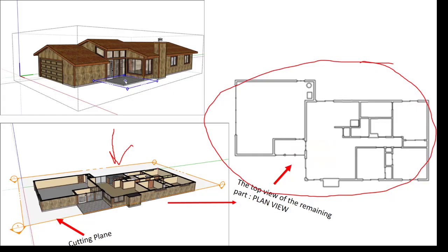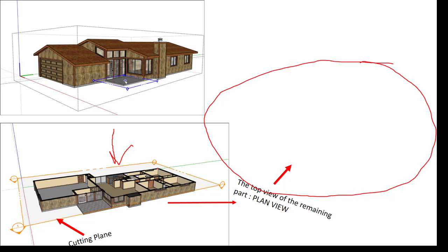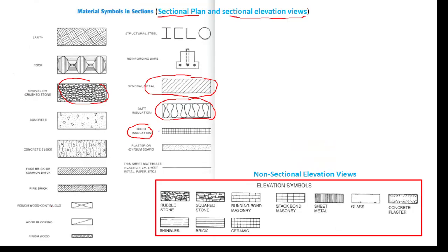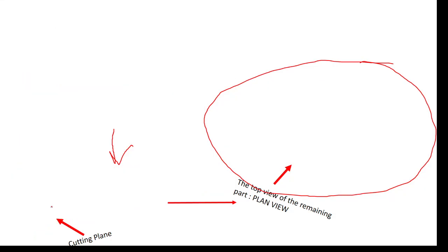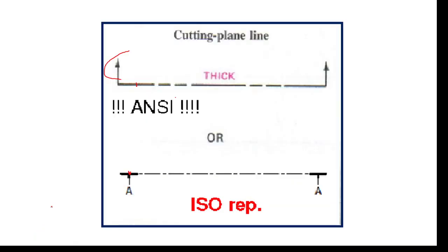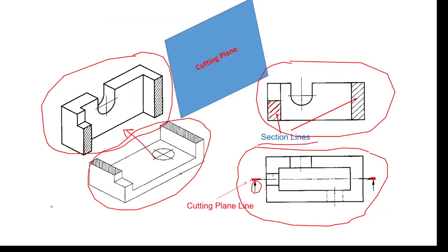If for outputting a sectional view you need to cut the body, you need to imagine the object as completely cut, yes, the cutting plane extends from one side to the other side. Yes, like this. This sectional view, from another point of view, is called a full sectional view. This is a full sectional front view.